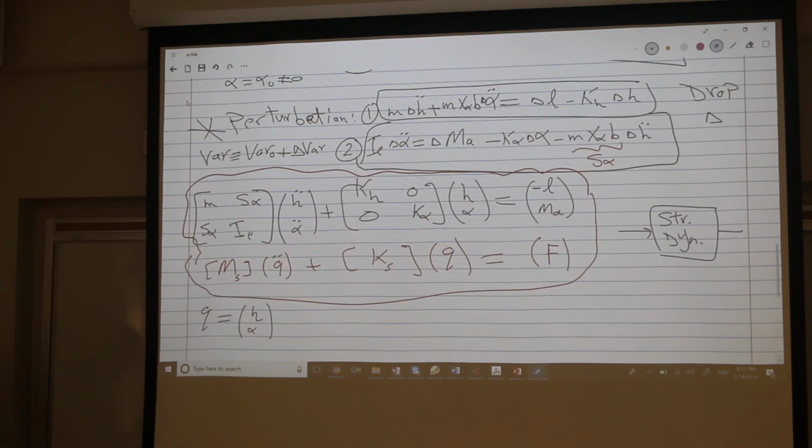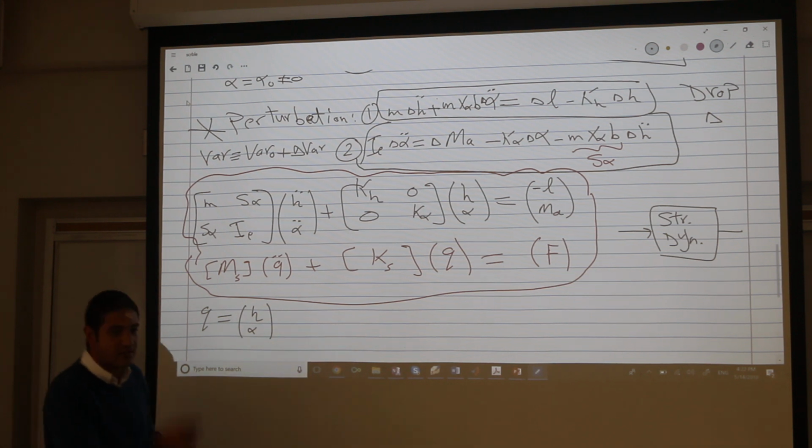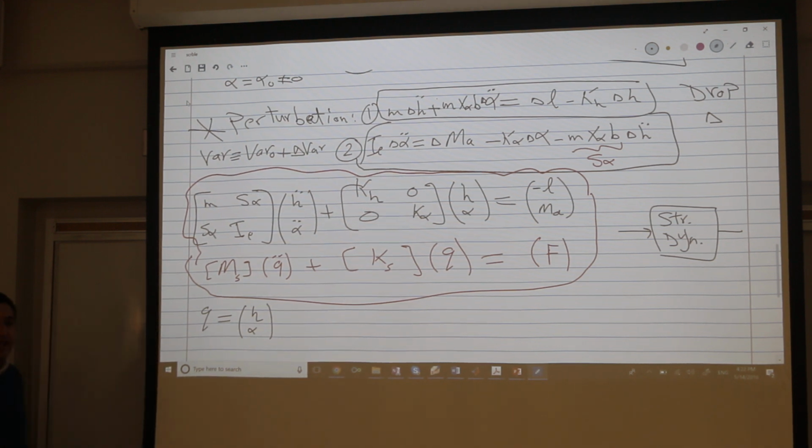So even if you have a nonlinear system, this is why, because some people say, okay, we spent our entire undergraduate and most of our graduate studies studying linear systems, whereas the world is not linear at all. Everything is nonlinear. Every system is nonlinear. That's correct, but for a nonlinear system, the linear analysis is sufficient. Any nonlinear system is stable if its linearized version is stable. Any nonlinear system is controllable if its linearized version is controllable. Observable if its linearized version is observable. Detectable if detectable, stabilizable if stabilizable, and so on. And where it's not, it's very, very few cases. Then you need to do nonlinear analysis, which is much harder, by the way.